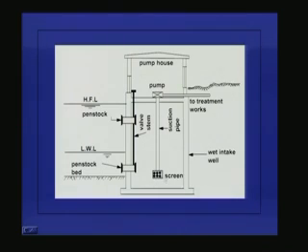having the function of screening the fine material from entering into the suction pipe and consequently into the pump and then damage the pump. Now, this level here, the screen level or the bottom level of the suction pipe, should be below low water level, and there should be some sufficient head available here, otherwise there could be an air entrainment. Now, this is called an intake well, and the water level in the intake well will be slightly lower than whatever is the prevailing water level in the river.